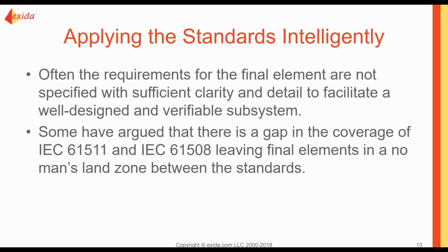If we look at 61508, the devices are going to have a detailed 61508 SRS, but they're going to address only the valve properties, or only the actuator properties, or only the solenoid properties, not the properties of the entire integrated system.